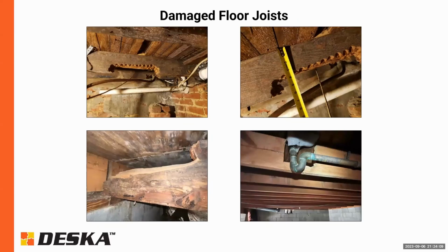So I'm sure you guys see these floor joist alterations a lot. Some people use saws, some people use drills, and obviously this is not acceptable. There are limits to where you can notch or bore a joist or a beam, depending on the type of beam or the type of joist.